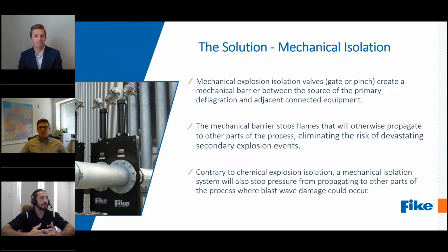The mechanical barrier stops both flame and pressure. So it's a little bit different from chemical, which only stops flame but not pressure from propagating. Mechanical barrier will stop both flame and pressure, which can save upstream and downstream equipment from any type of additional blast wave damage.